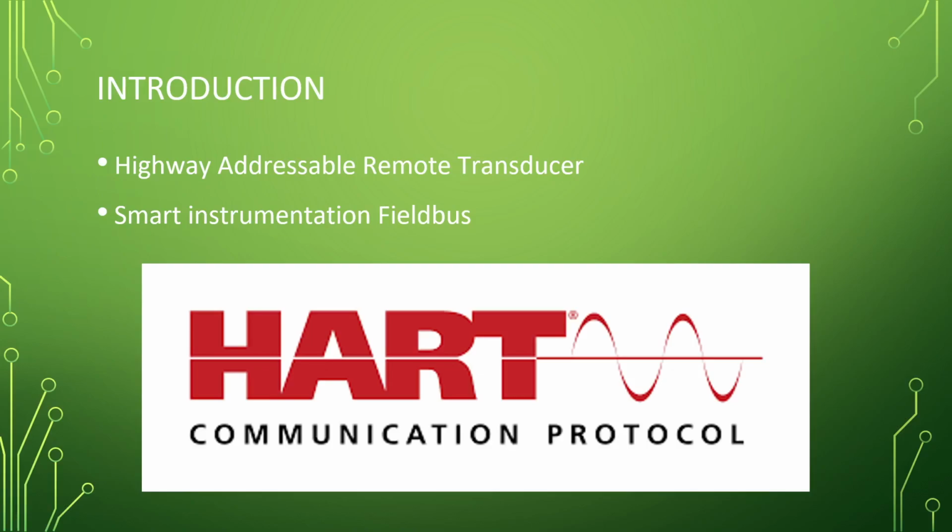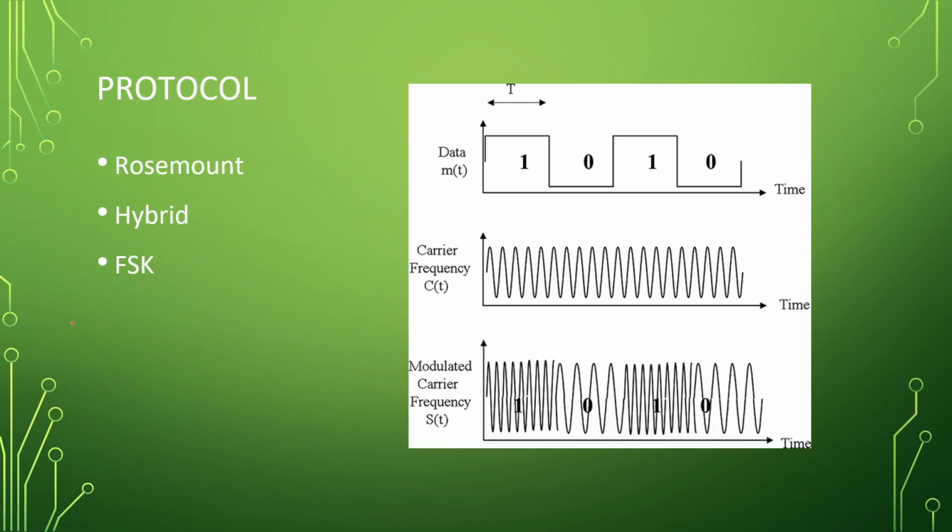We can control these sensors in all sorts of ways, which is very, very convenient if you ask me. And this is a hybrid, right? We're dealing with an old analog system, which is 4 to 20 milliamps, and then we're adding a digital system basically on top of that. So it is a hybrid system. The protocol we're using reuses the 4 to 20 milliamp, which is nice.